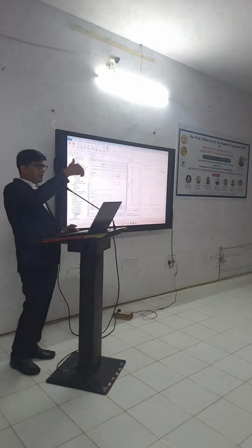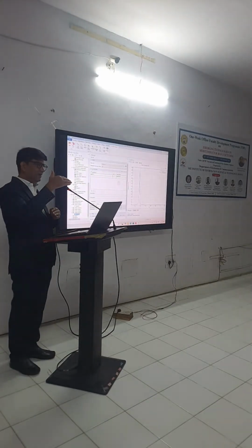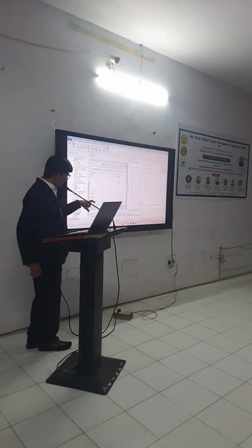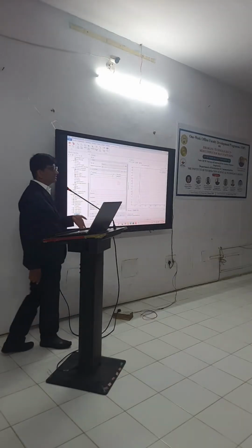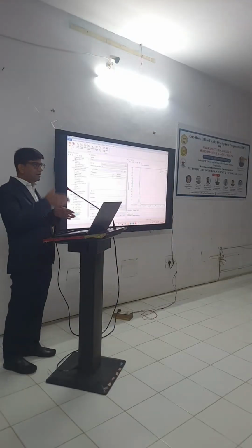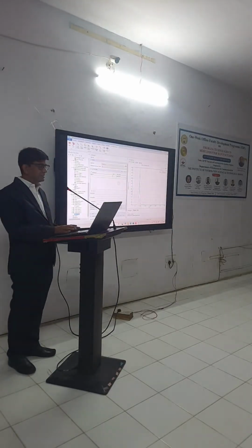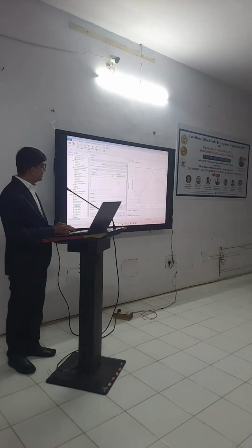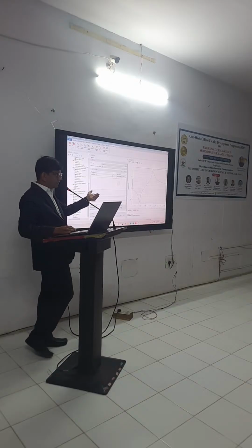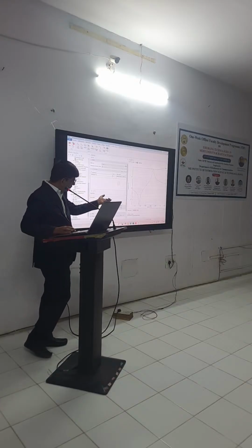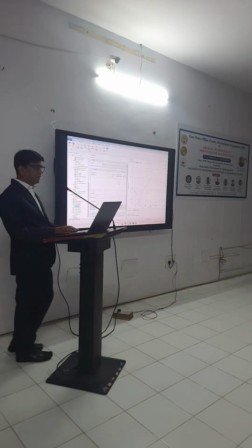Sir, you told me, why are you taking the log value? If you are not taking the log value, our response is like that. There is a very small dip at the resonant frequency. If you take this as a logarithmic graph, we have a sharp dip for my resonant frequency and anti-resonant frequency. So now you can see this is my frequency response for the range of 1.29 to 1.42 gigahertz.